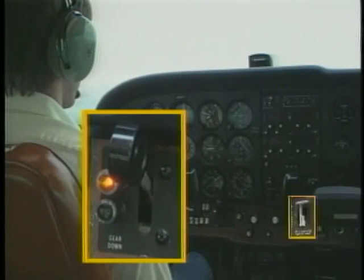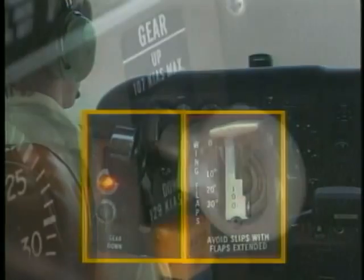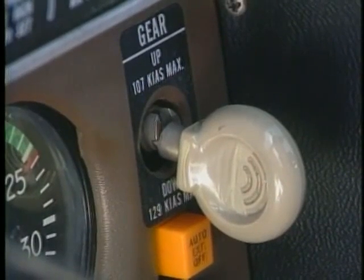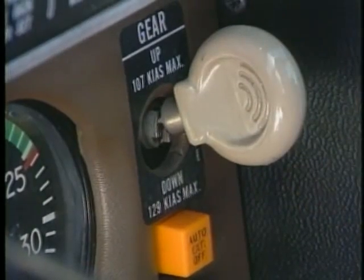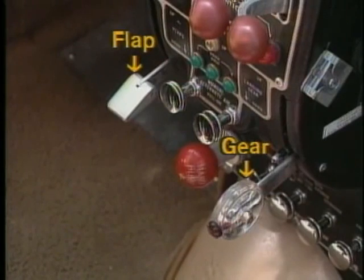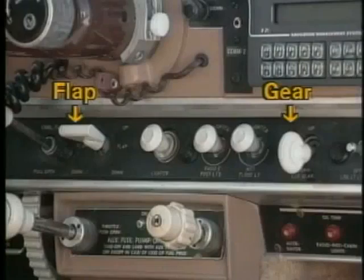Even though the gear and flap levers are shaped differently, a few pilots have thought they were raising the flaps, but inadvertently raised the gear. To prevent this from happening, most manufacturers have included a safety detent in the lever assembly. In order to raise or lower the gear, you must lift the lever over this detent. When transitioning to a different aircraft, make sure you're familiar with the layout of the controls. Some aircraft have the location of the gear and flap handles reversed.